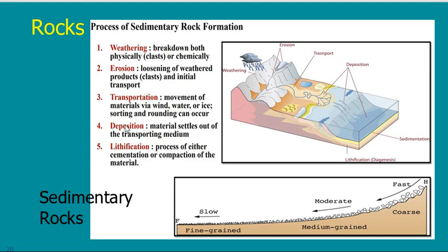Then comes the deposition phase. What is deposition? This material is swimming or carried inside water. It will not be carried all of the time. When the velocity of water starts to decrease, the bigger material starts to fall down, and the smaller material will continue to be carried with the water till the velocity decreases again. Then the slightly smaller material will fall down, and so on till we go to the end.